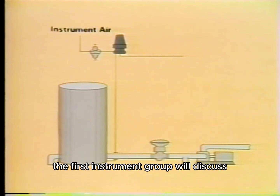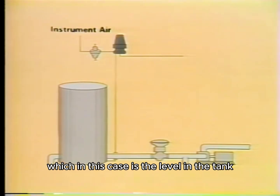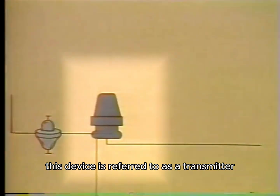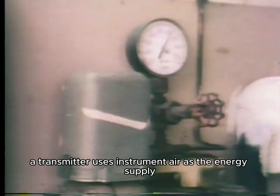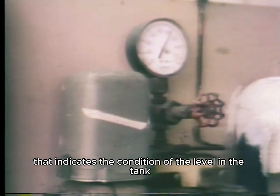The first instrument group we'll discuss is designed to monitor a process variable, which in this case is the level in the tank. This device is referred to as a transmitter. A transmitter uses instrument air as the energy supply source to produce a pneumatic signal that indicates the condition of the level in the tank.